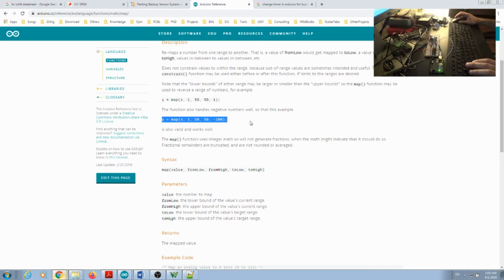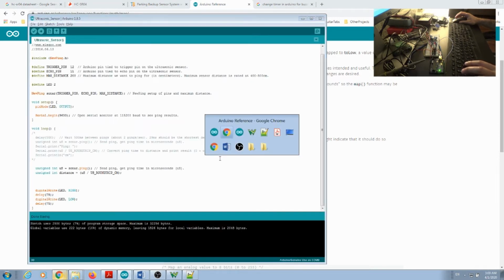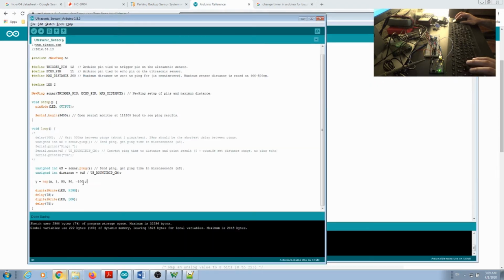So I'm going to copy this, go back to my code, and unsigned int, this is going to be my alarm. I'm actually going to declare this here and have the alarm declare that variable and initialize with the value. I'm going to say by default is going to be 1000, and this is going to be related with milliseconds for our LED to blink.